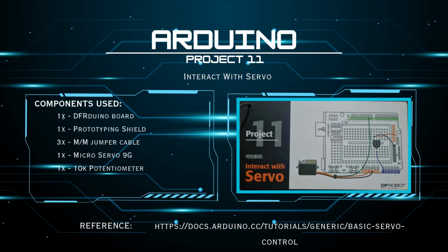In the previous project, we learned how to turn the servo to a specific angle using external signals. In Arduino Project 11, we take it one step further by using a potentiometer to control the servo motor's position. By rotating the potentiometer, we can change the angle of the servo in real time. This project introduces interactivity, where the servo's position depends on the input we provide through the potentiometer.